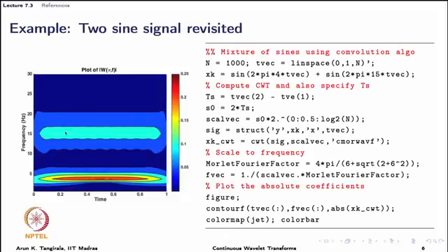One point that you should observe, whether in this plot or the previous, is that if you look at the magnitude of the CWT, it is very small at the ends, that is, at the borders. This indicates, or probably compels you to believe, that the signal really did not exist at this particular frequency, for example, in these initial portions, but that is not the case. We know that the signal exists right from the beginning, that is, this frequency component exists right from the origin and continues through to the end. So, why is this happening? Because of the border effects associated with the convolution operation.